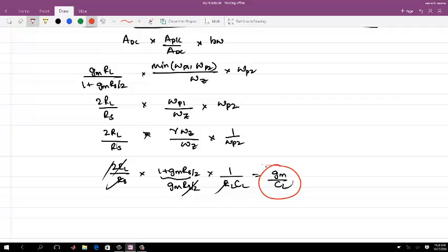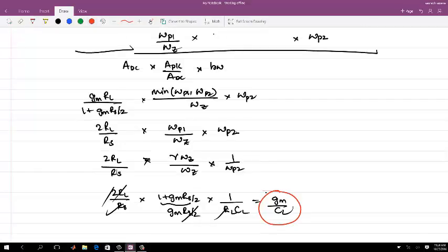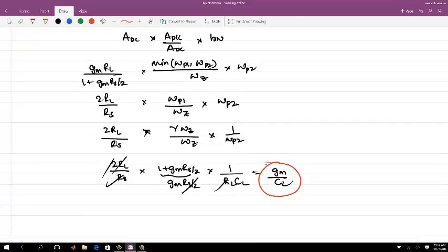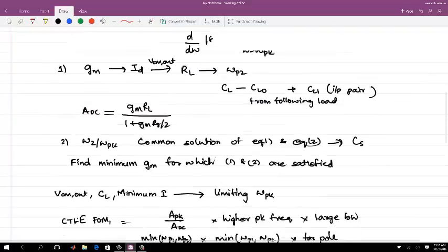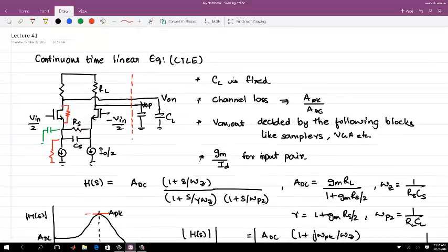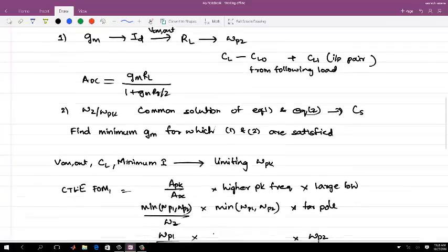Okay. So can you do anything to get rid of the CL? Or if you still want to increase the bandwidth of the system, what should be the first way to do it? Pardon? Tune it with the inductor. So let's tune it with the inductor, at which place? You have this load resistance RL, which is going to be there for a DC gain. Capacitance CL is coming on its own. Where will you put the inductor? Series with R, series with C. Okay, so you can work out both the cases, whether it is series with R or series with C.